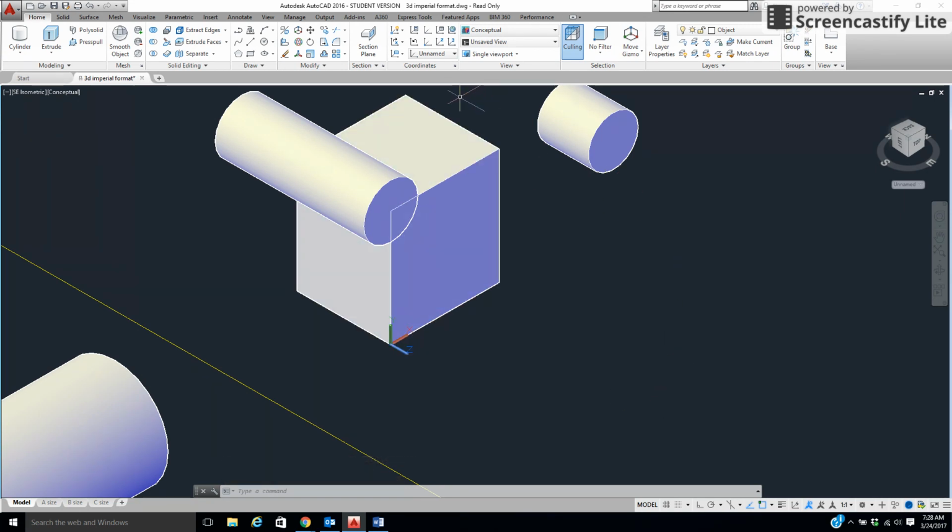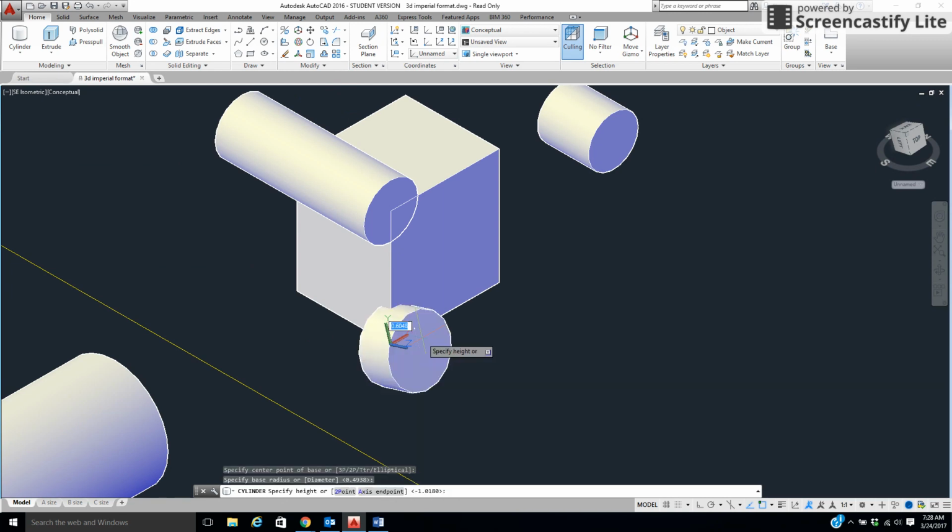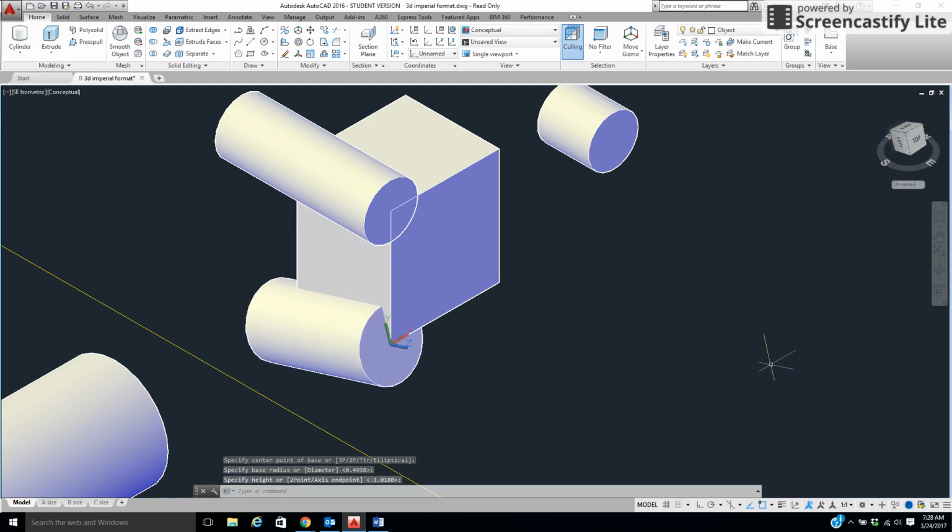Another amazing one with your UCS is this one here, X, Y, or Z. This allows you to rotate your UCS whichever way you need. Such as, if I say I want to rotate my X, watch what happens. See how this comes this way and it goes back? So I can type in an angle, I can pick, I can do a lot of different things. Remember, this is going to be our negative, this is going to be our positive. So we can change our UCS along those lines. Now watch what happens to my drawing. Look what happens now. See how that works?